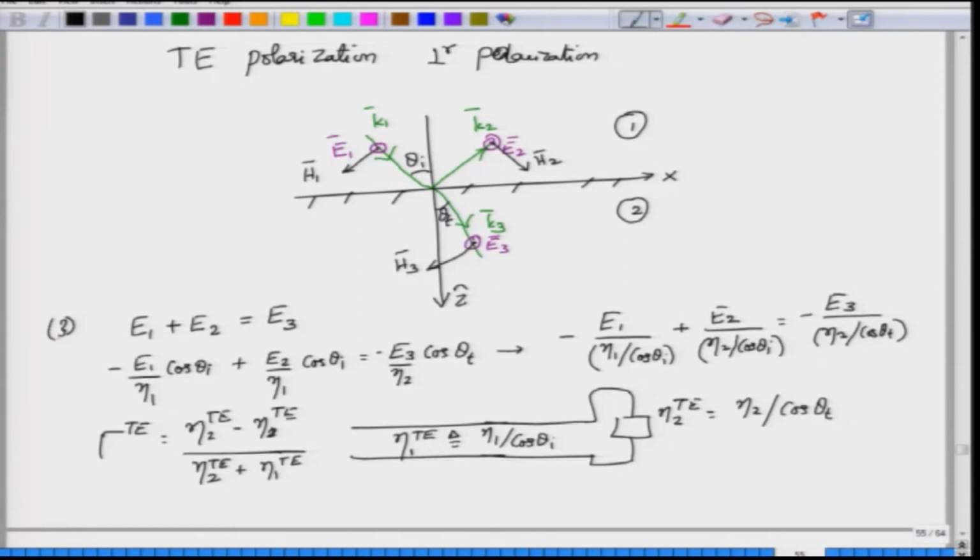We will call this set of equations 3 and 4, which basically express the boundary condition. So solving for this gamma TE, or equivalently tau TE, from this set of equations is as simple as writing down the appropriate reflection coefficient expression for the transmission line case. A longer calculation indeed confirms that what we have written is true.